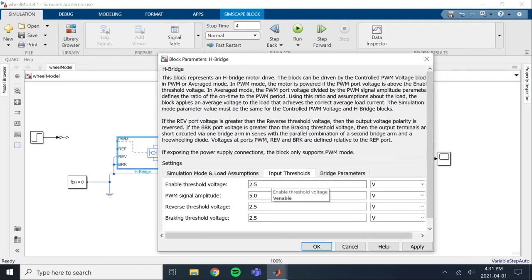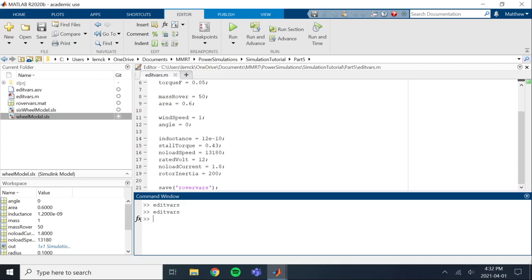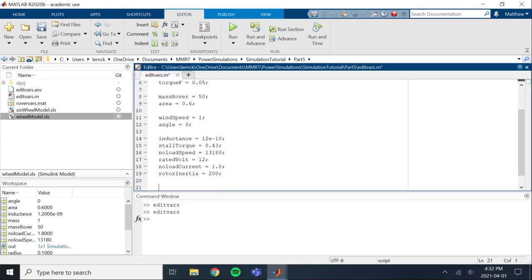But what we are going to do here is we're going to set this to PWM volt divide by 2. We're going to set this to PWM volt. This is the PWM voltage that we're actually going to be using. These other ones we're actually also going to set to PWM volt divide by 2. Not that we're using them, just good practice to set them to half the PWM voltage. Now that we have those variables set up, we need a PWM voltage. So PWM volt, set that up to 5 volts.